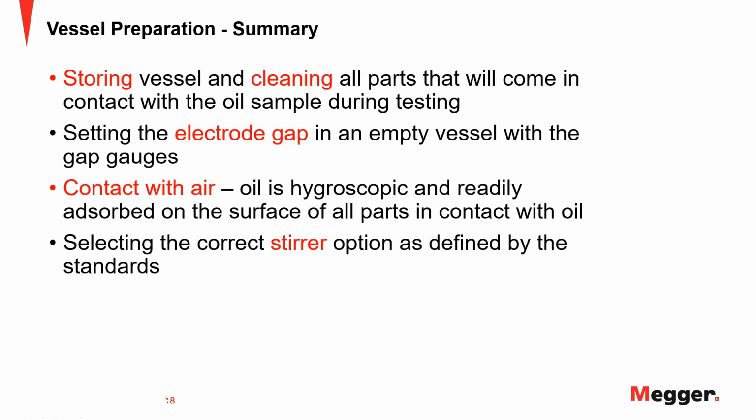Okay, so that's the vessel preparation in summary. We've covered storing the vessel and cleaning, but cleaning all the parts that will come in contact with the oil sample, not just the vessel walls, but every component that comes in contact. Setting the electrode gap is key to making sure that you have the confidence that the test results will be what you're expecting them to be.